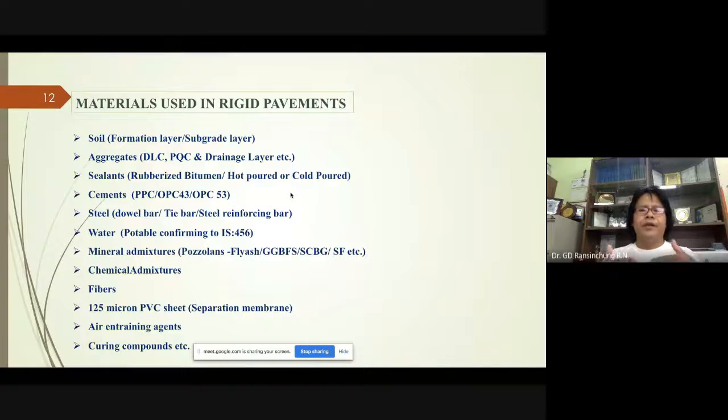Now, the selection of mineral admixtures again depends upon the requirements of the concrete mix. Silica fume is a well-established pozzolan, which has a substantial amount of siliceous content in comparison to fly ash and GGBFS, but it is expensive in the market.